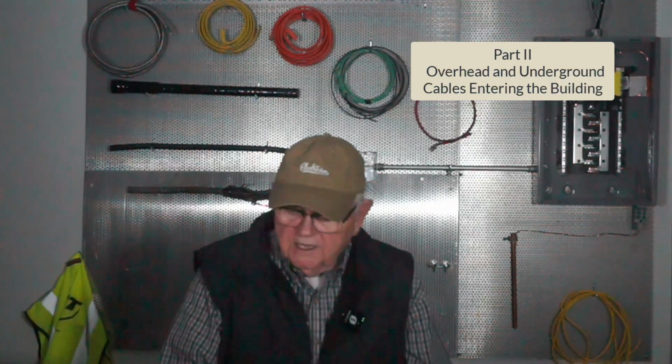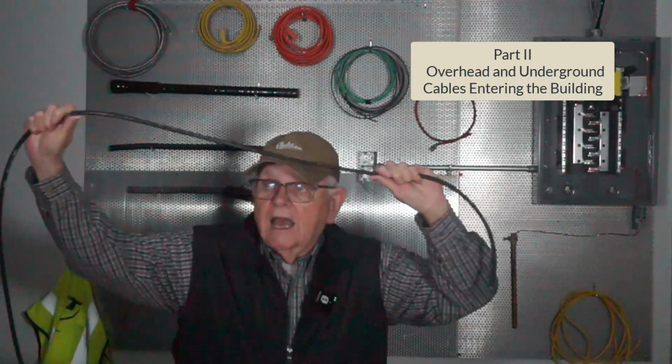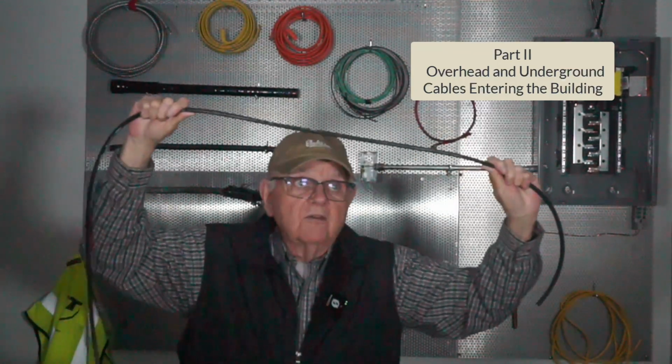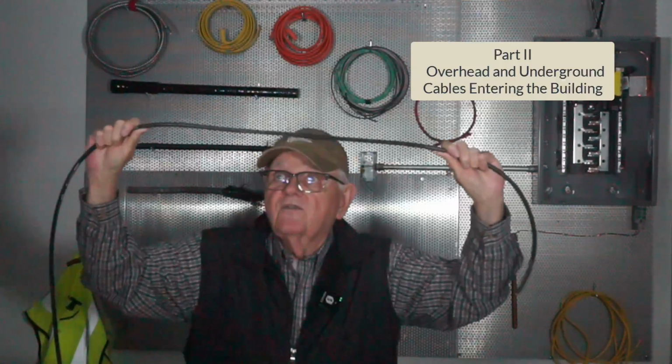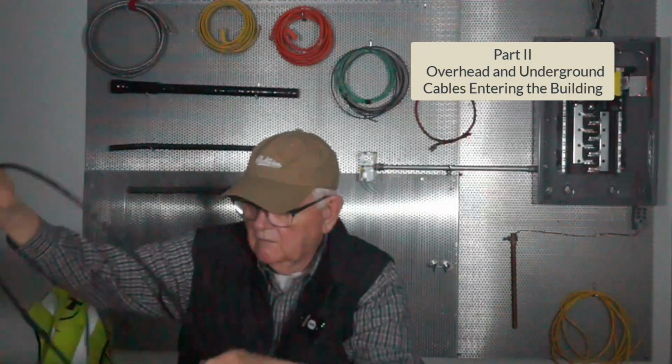When I go across, if I'm stringing this across over a roof, wherever the highest part on that roof that this goes over, this fiber optic cable must be at least 8 feet above that. And of course, as usual, there are always exceptions.